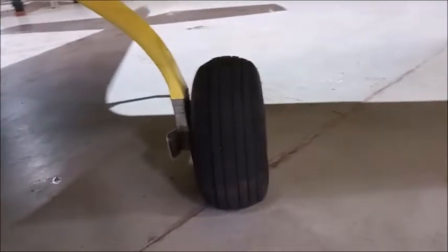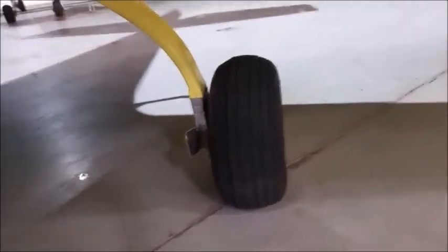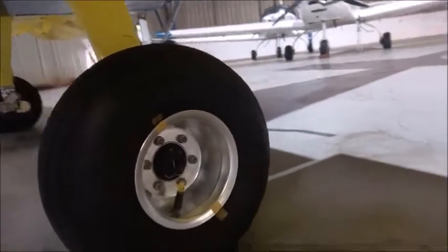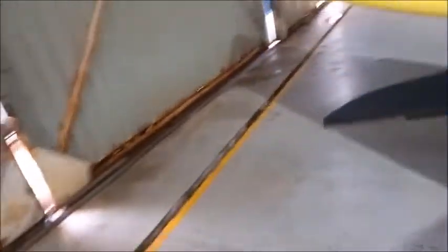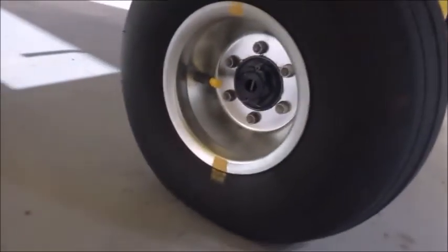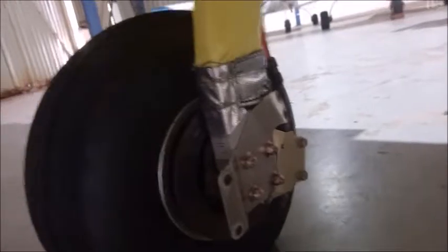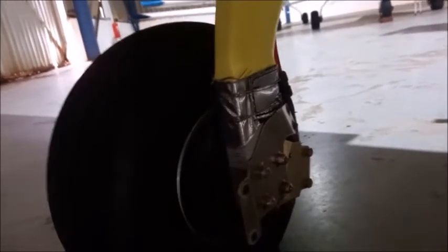Okay, then coming down again, we're just checking the back wheels, the two back wheels. The tread is looking good. Coming across this way, you can see all the bolts are in position, so that looks all good. We've also got to check the other wheel, to make sure that all the bolts are secured. The tread is fine, and over there the bolts are secured.